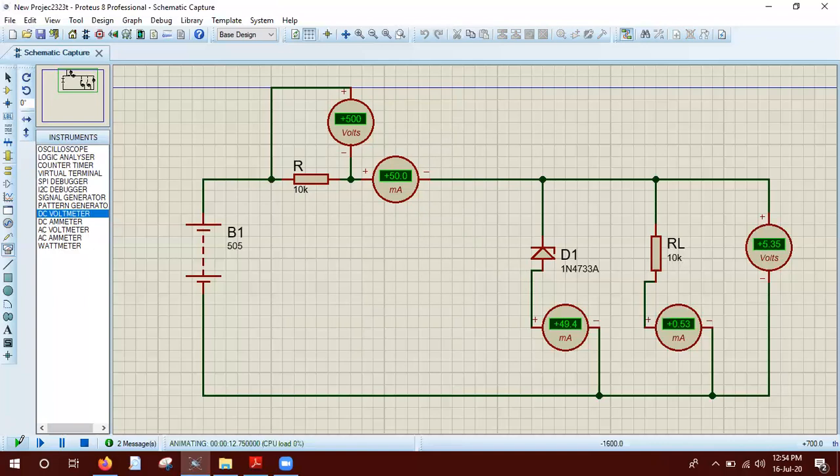Okay, is it clear to you? Yes, sir, absolutely clear. But interestingly, you see that we are increasing so much voltage here, but the output voltage is not changing at all because there is a Zener diode. So that is the purpose of a Zener diode, to make the output voltage fixed. Just take a particular voltage Zener diode, your output will be fixed.